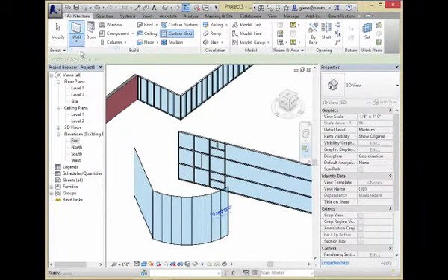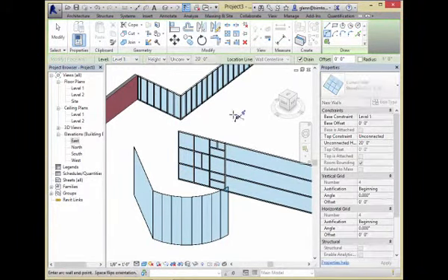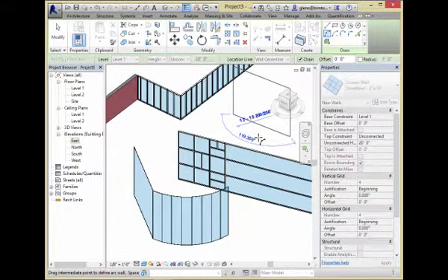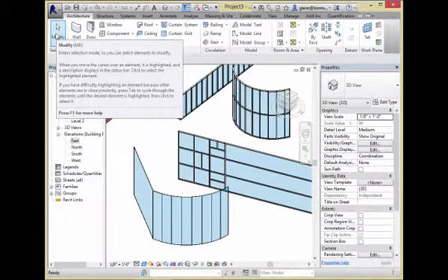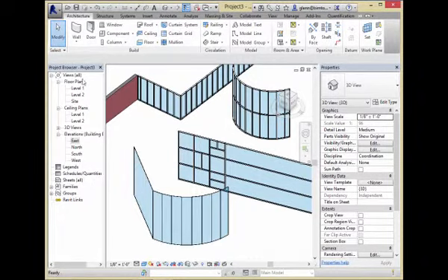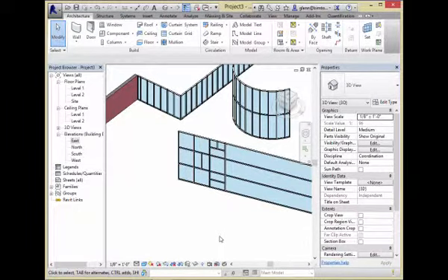So again, if I do the pattern-based wall, that should follow the curve pretty well, because at only 3-foot panels, it can follow the curvature. Those panels are small enough they can actually get around there. So you've got this choice of building them up from scratch or doing them pattern-wise. But let's talk about the hybrid of the two. If I have this wall over here and it's got all these 3-foot segments, honestly, that's going to be pretty good for about 90% of what I'm doing.